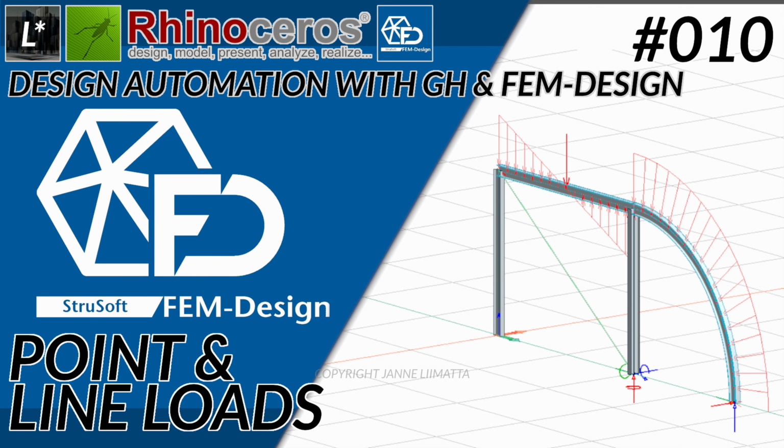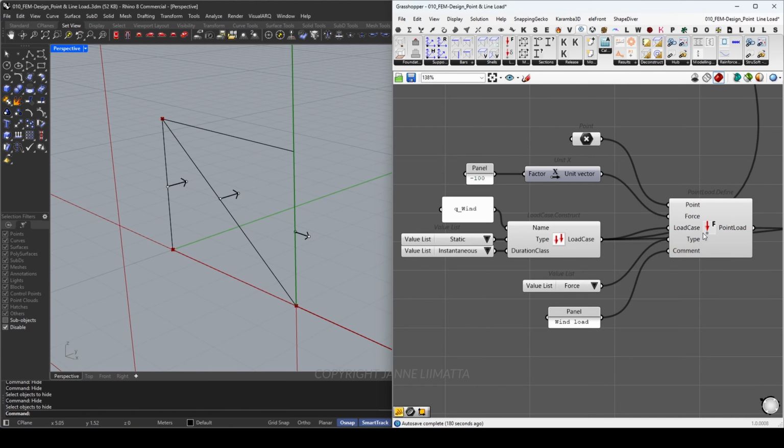Let's add some loads to our model. Use pointLoad.define to create a point load. You need to define the insertion point and force as a vector. I am applying 100 kilonewtons of force in the negative x direction.